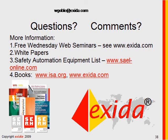And if you have high quality data, you don't have to put in redundant components unless your PFD calculations say that you must. The fact is, I don't want to be too optimistic here, this is not a loophole to reduce your designs. In fact, your PFD calculations 95% of the time will tell you you must add redundancy. I hope that answers the question.